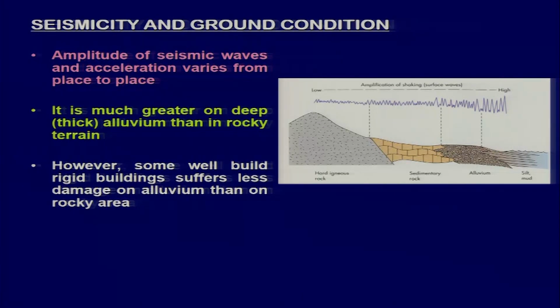BIS code as a building code which is assigned for that particular region, and that is one of the important parts where the geophysicists and even the structural engineers study the accelerograms, because they want to understand what was the peak ground acceleration by a particular earthquake which has occurred in the past or the recent past on